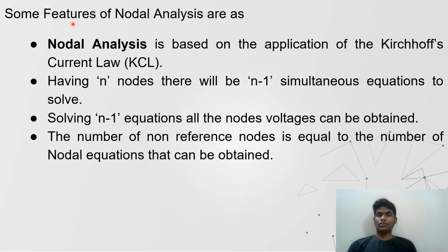Some features of nodal analysis: it is based on the application of Kirchhoff's current law, that is KCL. Having n nodes, there will be n minus 1 simultaneous equations to solve. Solving the n minus 1 equations, all the node voltages can be obtained. The number of non-reference nodes is equal to the number of nodal equations that can be obtained.